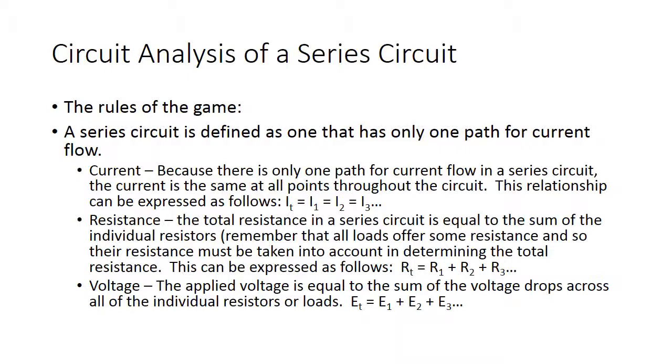So the point to remember is that in a series circuit, the current is the same at any point throughout the circuit, and that the current flowing through an individual load will be the same as the total current. All the current flows through each point in the circuit.